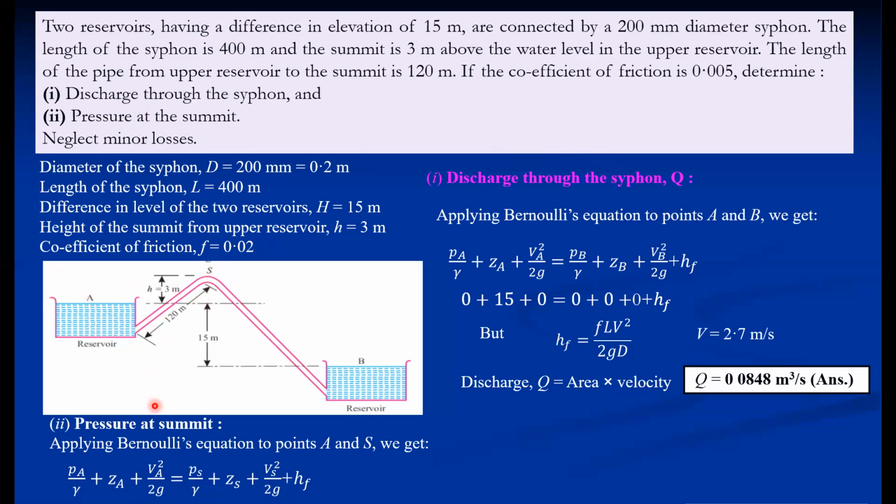Now here we have to be careful while considering the pressures, because most of the students make mistakes here. If we are taking gauge pressure here, then whatever this pressure is has to be a gauge, because pressure here is most of the time negative. Not most of the time, almost always negative. PS. So in most of the numericals these PS values are given, sometimes in absolute, sometimes in gauge, that is, a minus value is given.